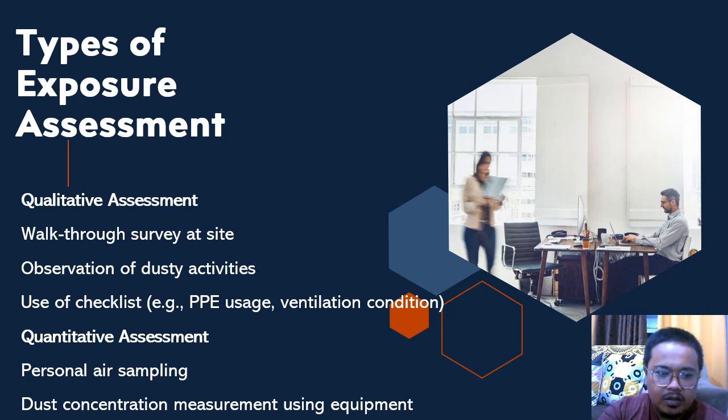And second, quantitative assessment. Quantitative assessment involves actual measurement of exposure level. This is done using air sampling equipment to measure the concentration of dust in the air. It provides more accurate data compared to the qualitative method.